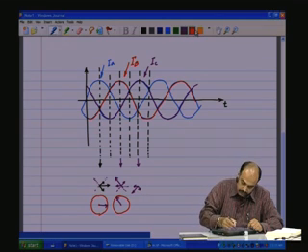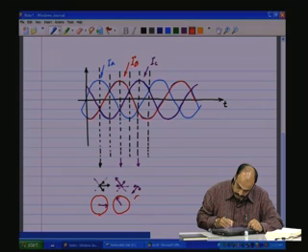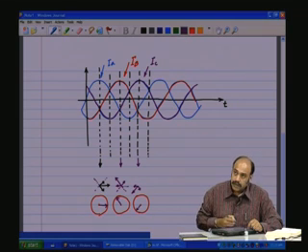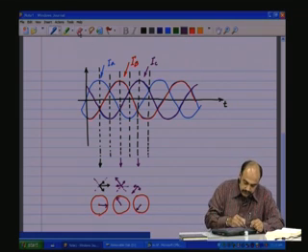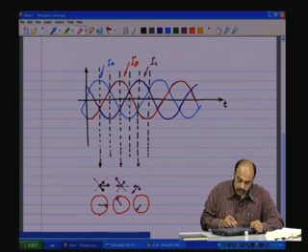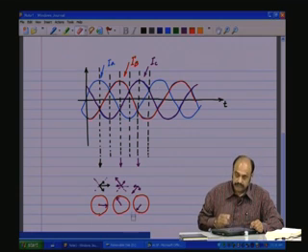So therefore you will have a flux which is in this direction. So you see that the resultant flux, as time progresses, it was in this direction, then it has rotated in that direction. So we have taken some crucial points in between to show that the flux positions are changing.